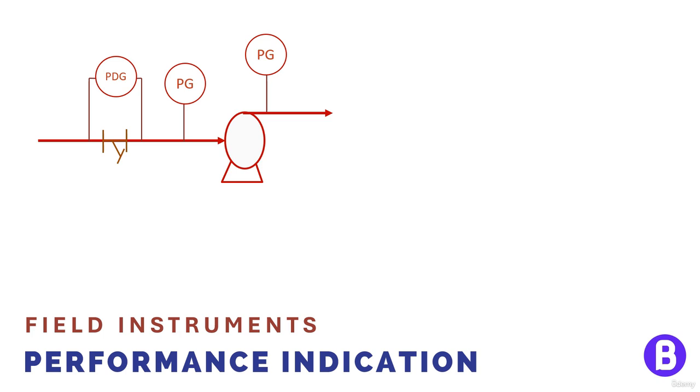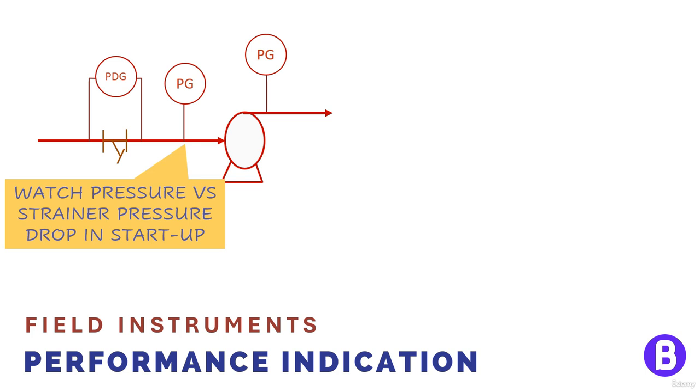So during startup, it's important to watch the pump suction pressure along with the pressure drop through the pump strainer. Once it reaches an unacceptable value, the pump should be stopped and the strainer should be cleaned. And this procedure shall be repeated until the pump can work safely.